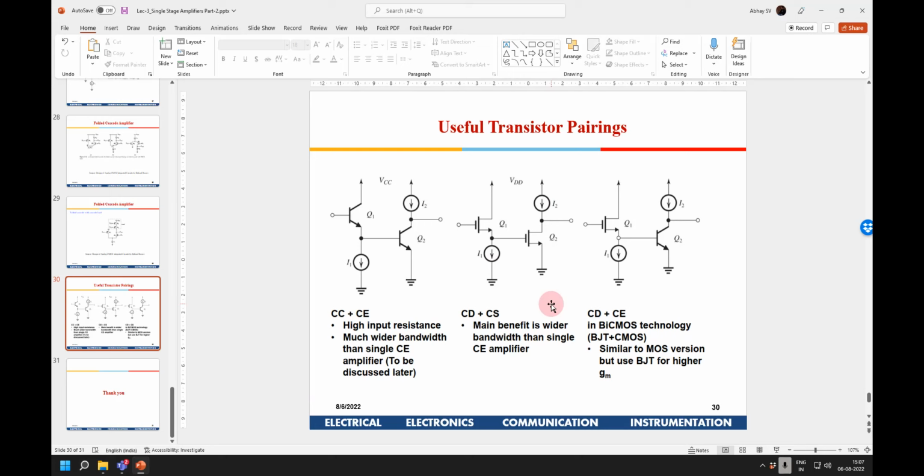When a high frequency signal is applied at the common drain, output will be at high frequency. It doesn't have a Miller effect. But the output of the common drain will be at high frequency, and that is the input to the CS. So that will create Miller effect, because Q2 is the amplifying MOSFET, so its gain will be reduced again. Yeah, correct.